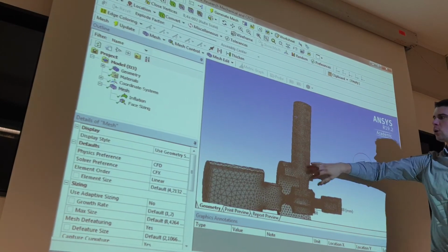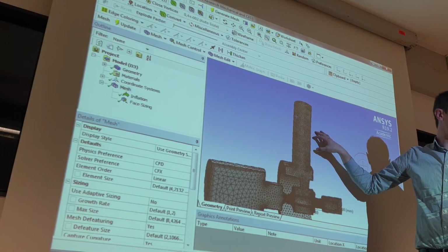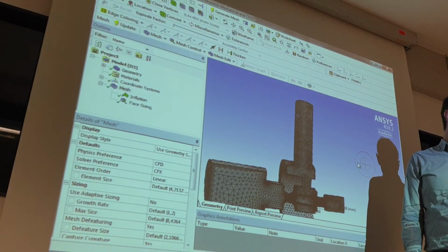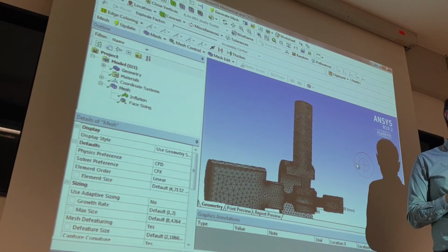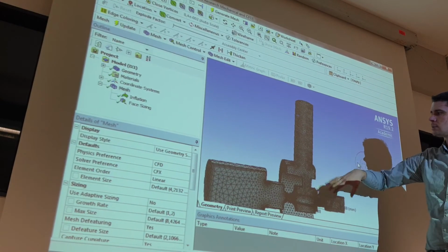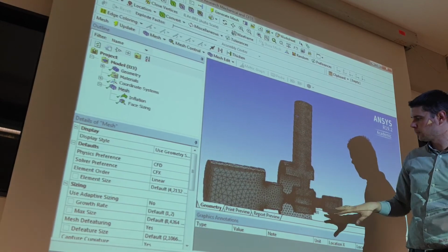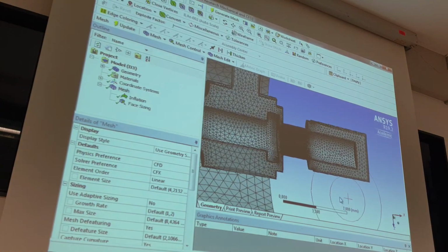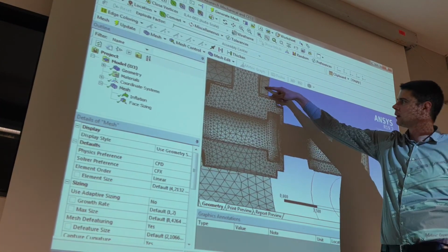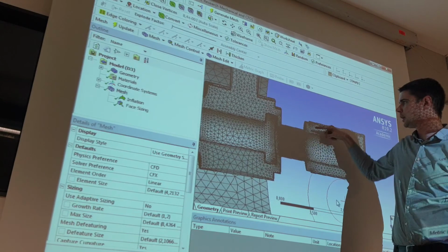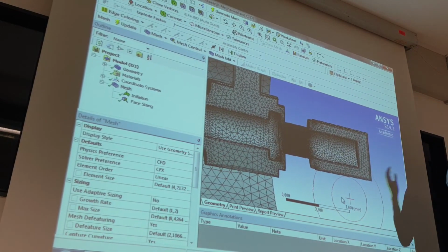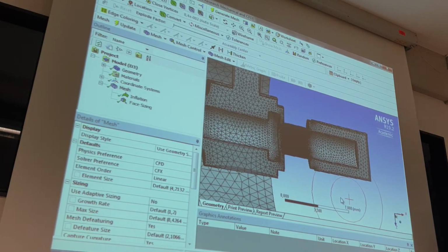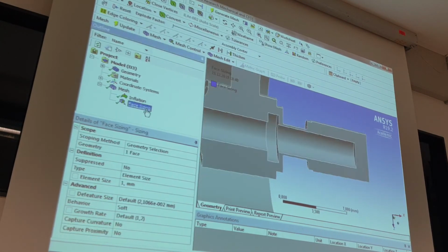I have here, I don't know, 30,000 elements, but I can slice it and make a sweep with 1,000 elements or 500 elements. So do you understand the same strategy? I can slice here, for example, then the other part I can use the sweep method. If I slice now like this, then I can use the sweep method again. I can save a lot, 100,000 elements. So I can save with hexamesh. So, okay.